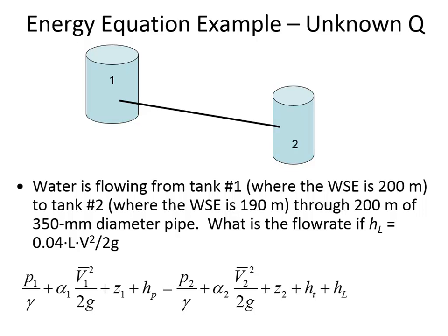I told you about the Darcy-Weisbach equation. This 0.04 is reflecting how rough the pipe is, and maybe it turned out that the pipe is made out of jagged, rusty material and it's very rough. That would increase the friction factor, and again, that would decrease the flow rate.